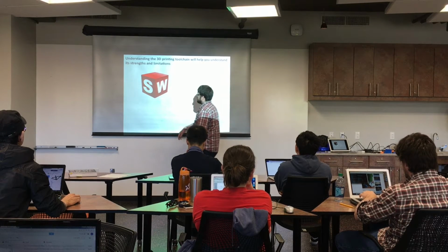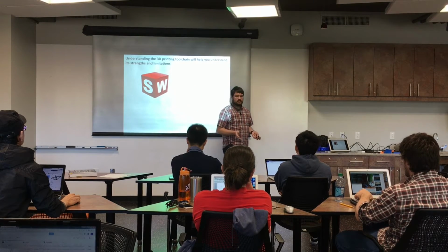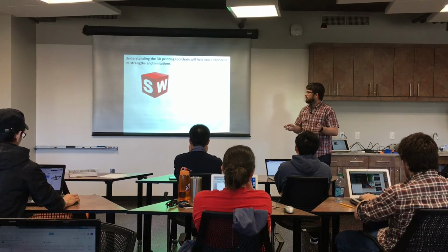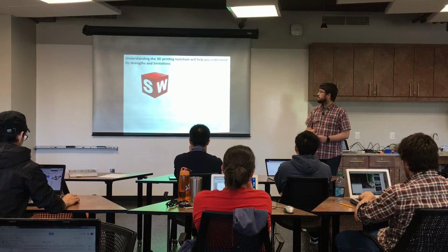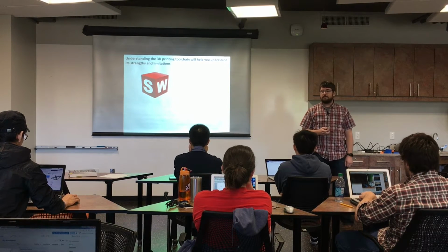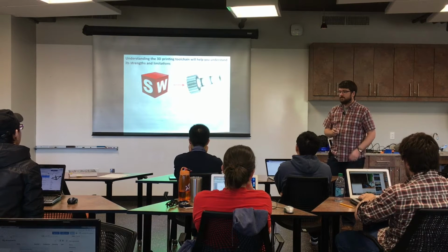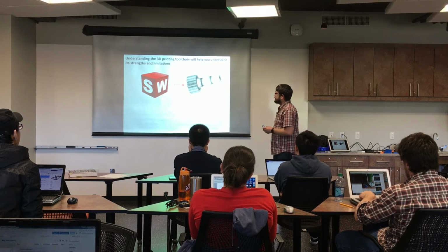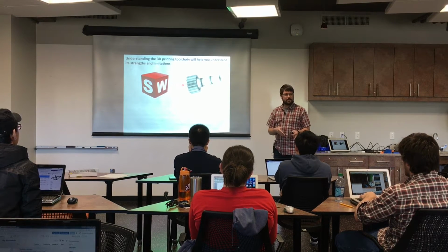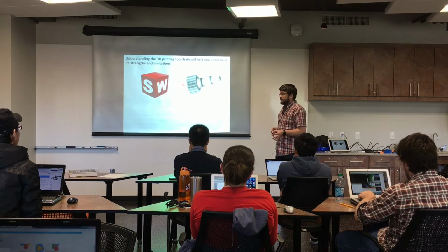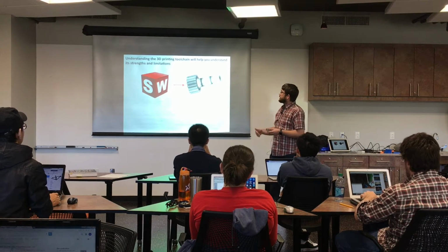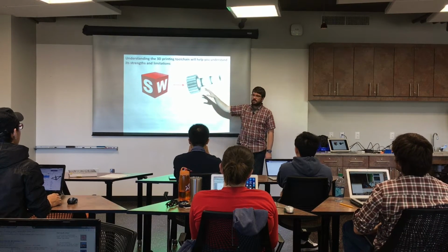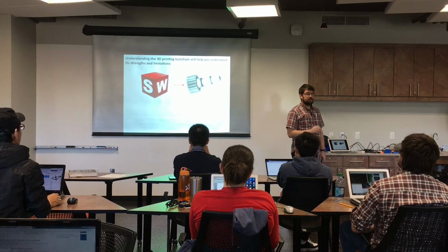But it all starts with a CAD tool. So this is the SolidWorks logo. It could be anything. I'll show you several CAD tools. But you do your part design in some kind of tool and generate a 3D model of the part. You then save that model as a stereolithography file, or .stl. And there's a lot of backronyms for what STL means. The most common one is standardized tessellation language, but you can see it takes the part and it breaks it up into this mesh, and that mesh is what's saved, and you can do that at different resolutions.